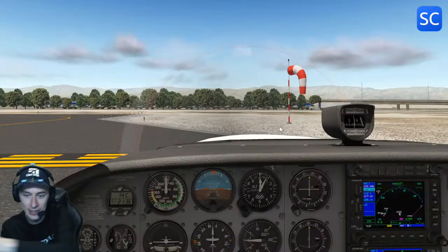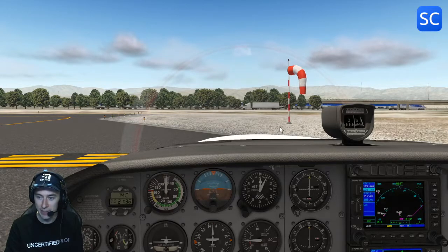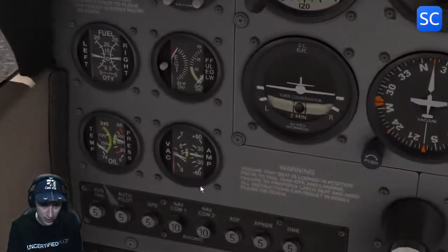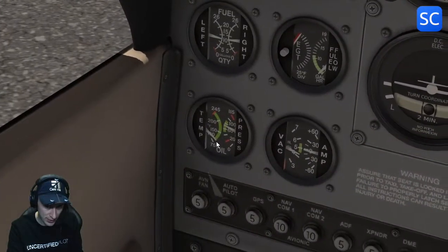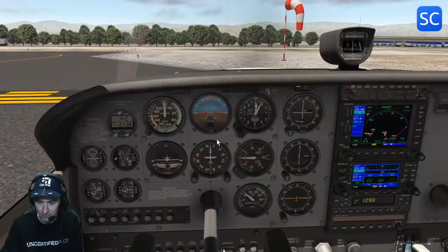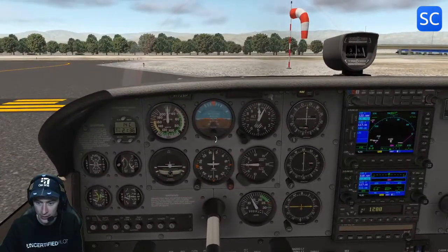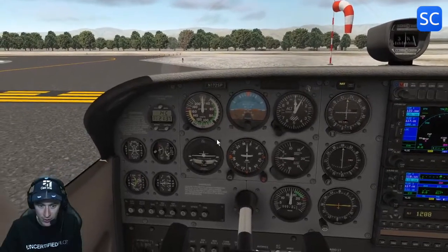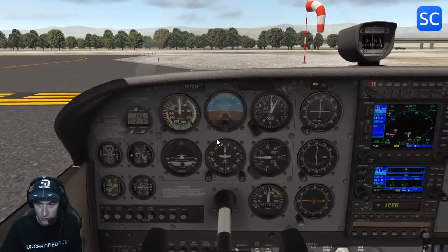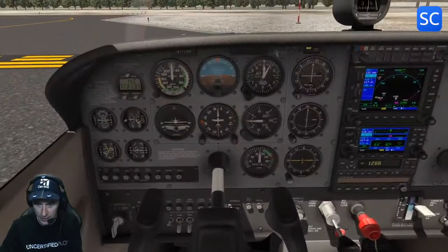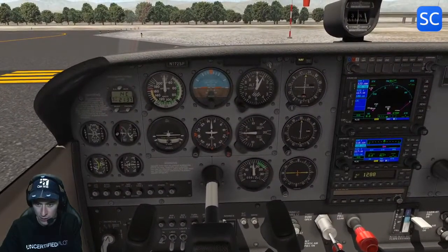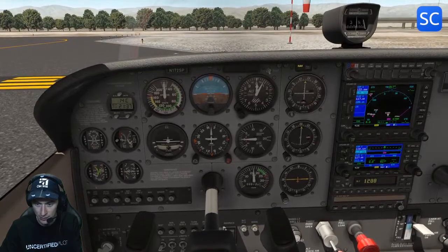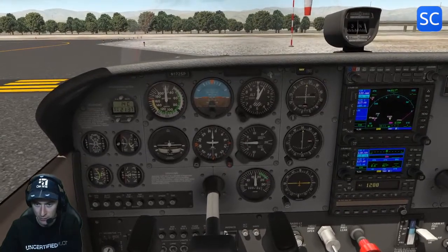Yeah, perhaps our engine is already warm. Hop into the cockpit quickly. Train passing by, or truck? No, train, I think. Engine, yeah, just barely in the green. Alrighty, so mixture full in. Let's go to 1800. There we go, no unusual messages, oil pressure still there, everything is stable. Looks good, left mag. Good enough drop, back to both. Right mag, good enough drop and comparable, good, back to both.